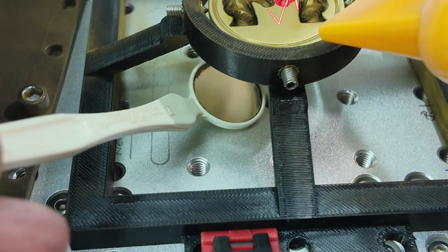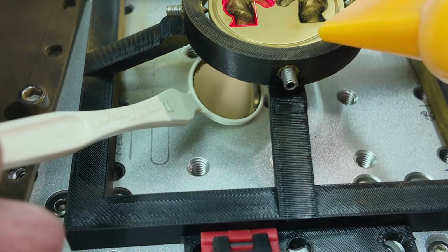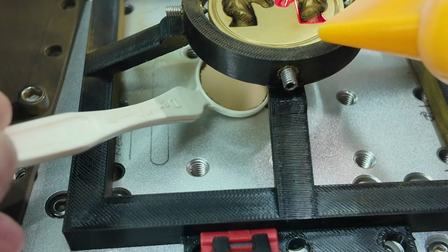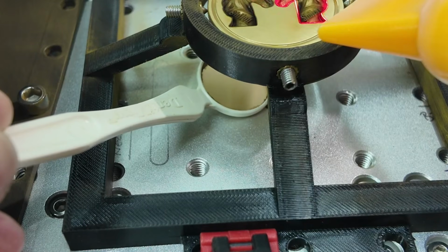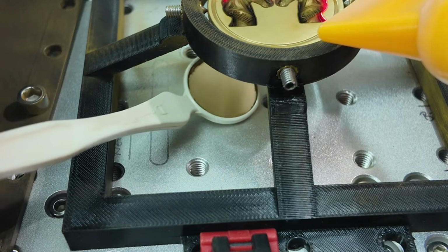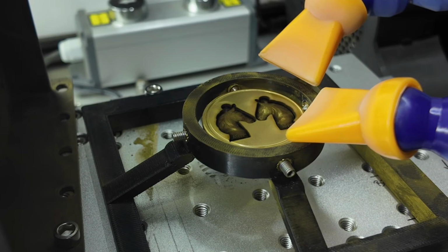So I'm just going to use those outlines that we created in the prior step. I'm going to alternate the red and pink layers there, and I'll just bump up the passes. I'll move it from 15 to like 50 and just alternate between those two until everything's cut out. I've run the outline and the slow line cut pass several times. I just upped the number to like 50 passes and ran it a number of times.